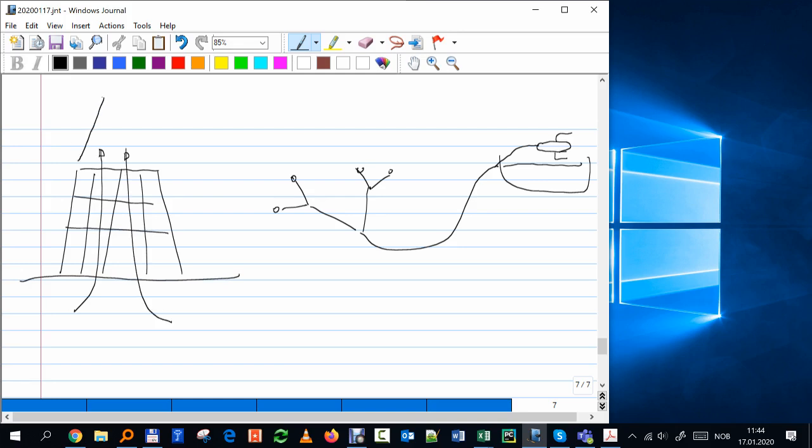And usually for this type of platform you have the drilling tower on top. So you have to be careful if you are producing from one well and you're drilling on the well neighboring it, because remember, we have to move a lot of equipment, BOP, in and out of the well. So if one well is producing, we like to avoid causing accidents. You don't want to be drilling on a neighboring well.